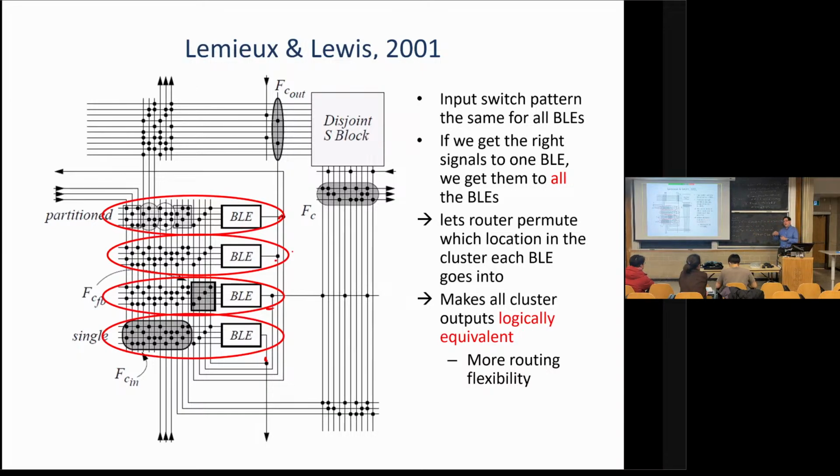from how I route to the output. And if those decisions are coupled, then it's more complicated. So I don't have to do this. Xilinx doesn't do this. Xilinx has a more irregular pattern still. It's more depopulated. And therefore, if they want to swap the outputs, they have to actually put another mux structure in there. And that's what they choose to do. So that's also a valid thing to do.